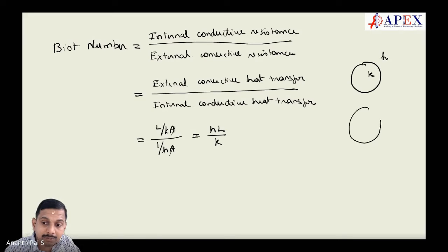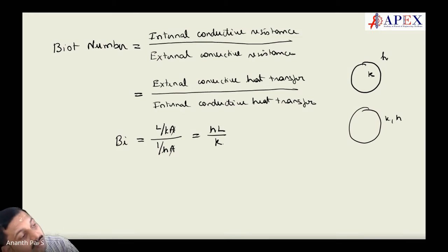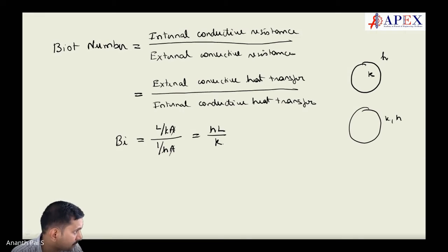This is Biot number; for Nusselt number, K as well as H is the fluid itself. If I put Nu here instead of Biot number Bi, K instead of solid will go to fluid. We will see the importance of Nusselt number later on. I'm just telling you all the things so that when it comes, you will relate and remember that Biot number and Nusselt number have a similar form.